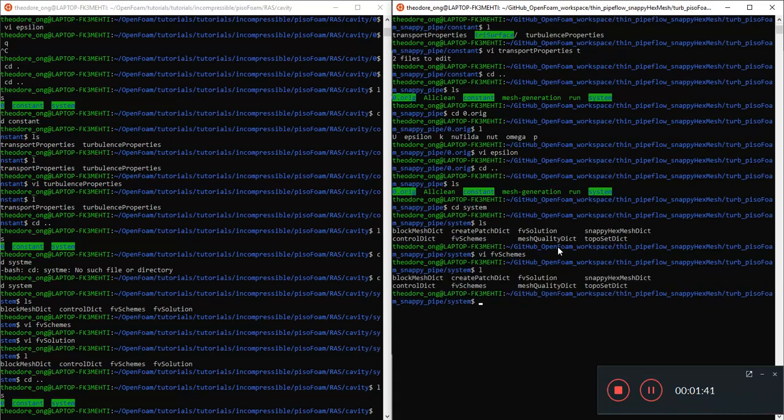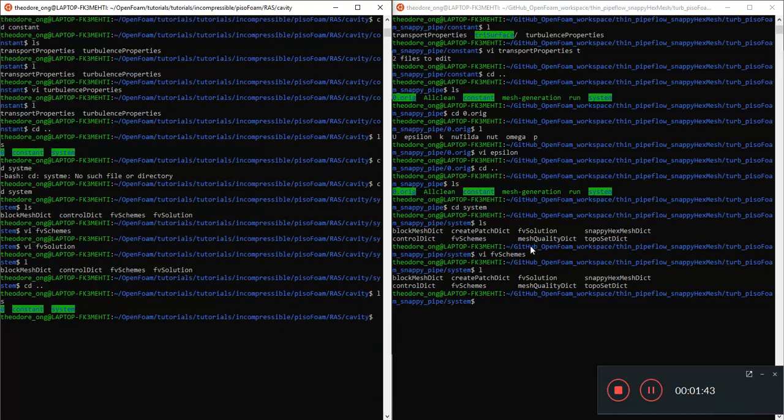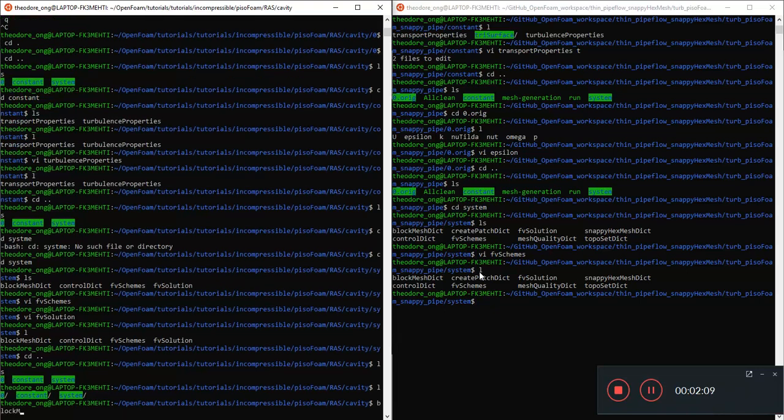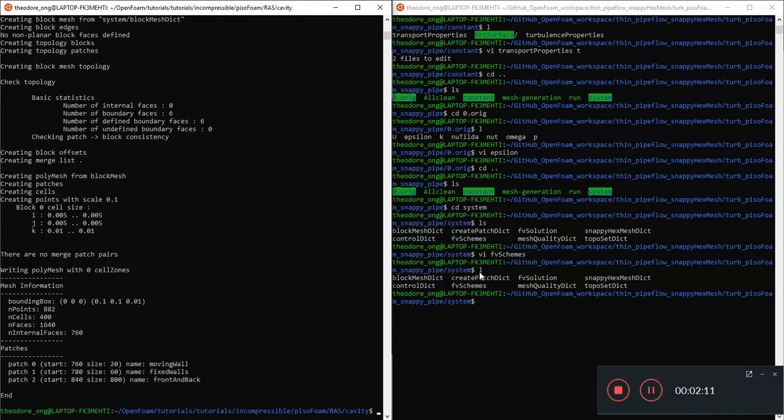Next step, we want to edit our files, at least the boundary conditions and the controlDict, because we want to simulate a faster flow, which is of course going to be turbulent. But before that, we'll just want to run a dry run of the cavity file. Let's see whether doing a blockMesh, and then we'll run pisoFoam.